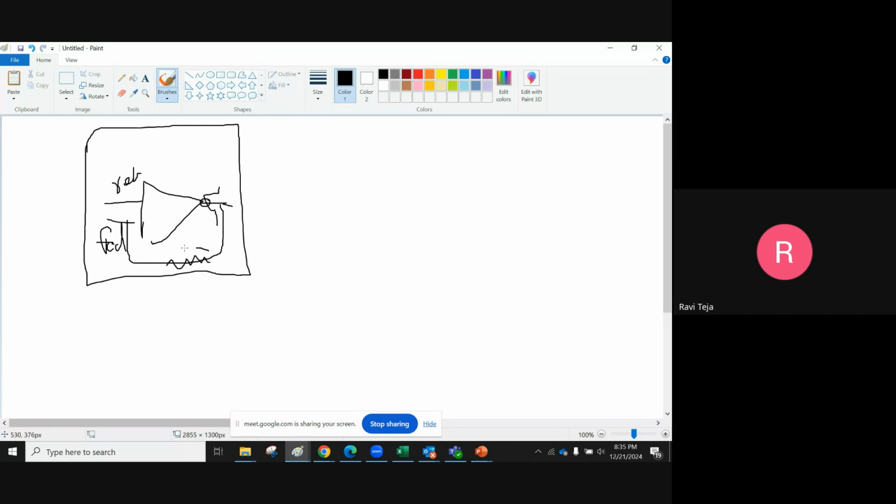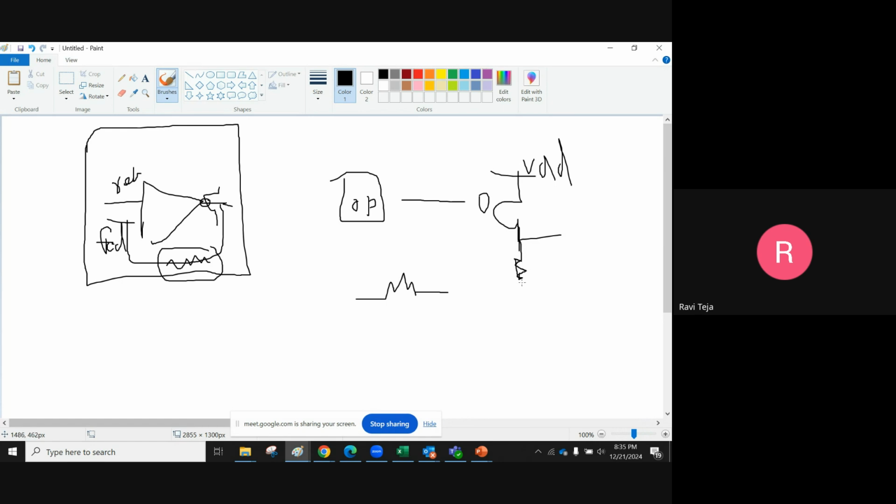Then this is a feedback resistance. So this is a regulator. In this regulator, we have one op amp, and we have feedback resistance. And then there is an output switch, which drains the load current here. And then the output is connected again to feedback resistors, and this will come to this. So this is Vref and this is the feedback voltage.